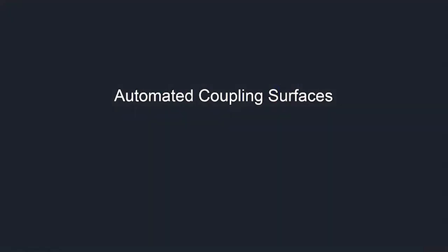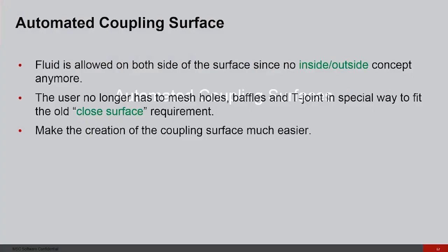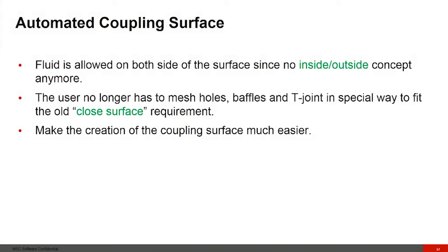I'm also going to be talking about the new features that have been added: automatic coupling surface. In fluid structure interaction, a number of shell segments interact with the Euler domain. So we have a section where the fluid and the structure are trying to interact with each other. The list of these shell segments is called the coupling surface, and it can consist of structure segments, but also has some dummy segments. Before, to simulate these interactions, we used the fast coupling approach, which is often used, and it requires some intermediate techniques and meshing techniques if you have the interaction.